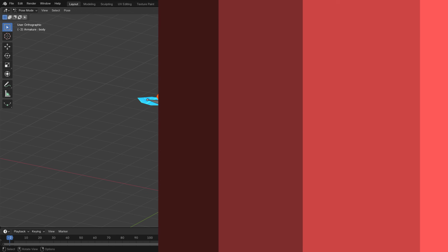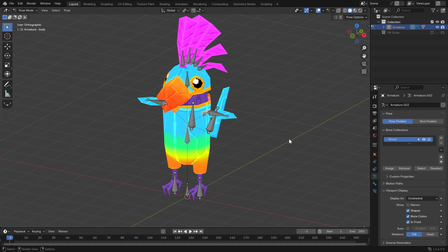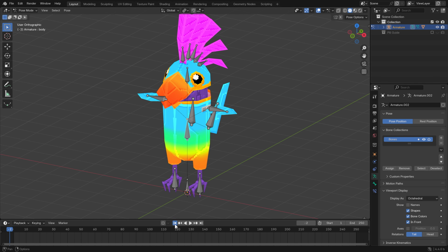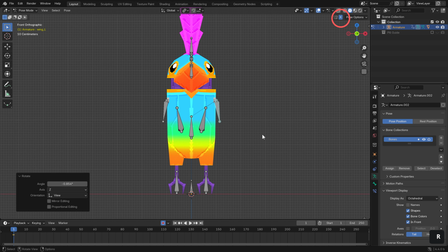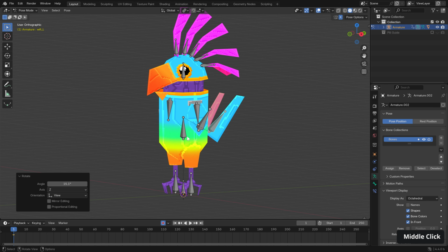Okay, good. What is the use of a rig without a little bit of animation? And we're going to go lo-fi on this and make it as easy as possible by setting up effectively 2 poses. So to start with, we need our start position. Make sure we are on frame 1 here and switch on our auto key. And let's just create the first pose. You can also switch on mirror pose as well to make it a little bit easier.